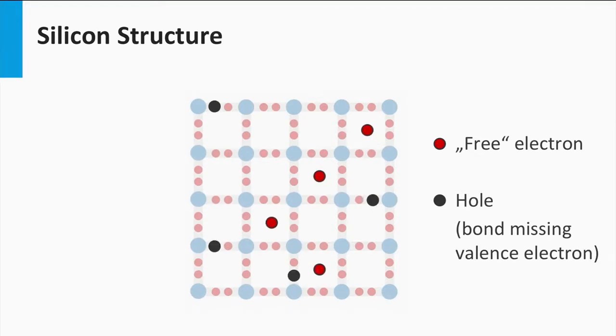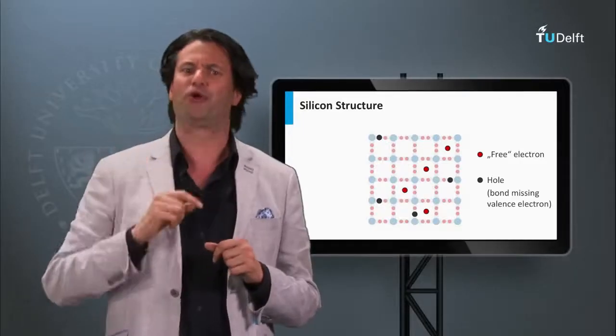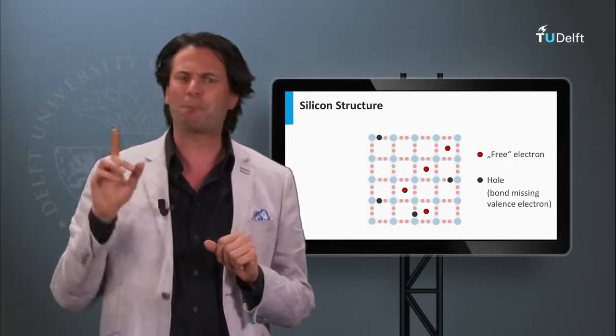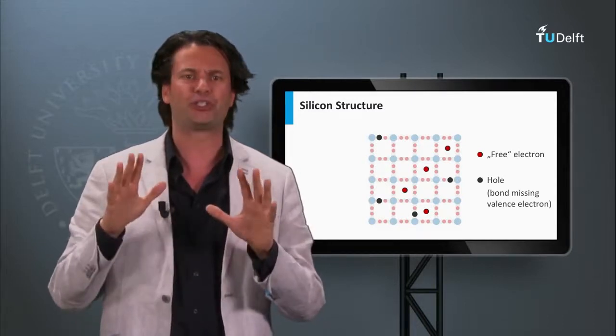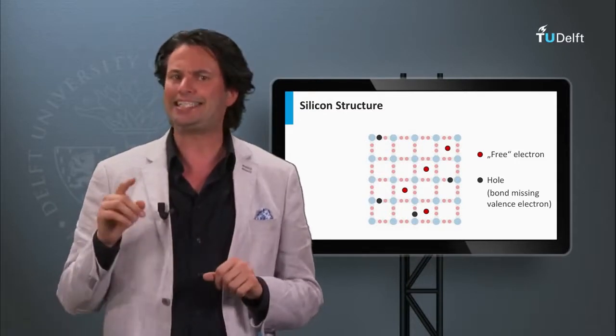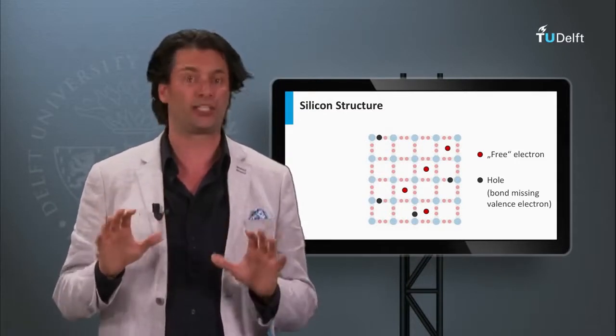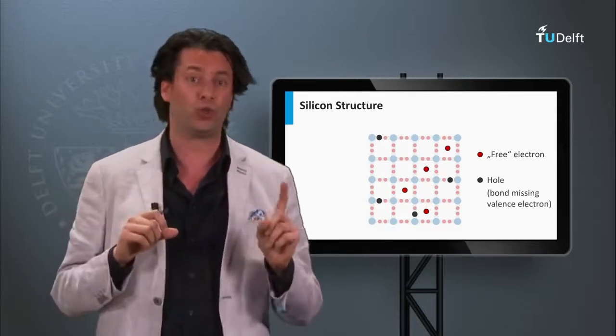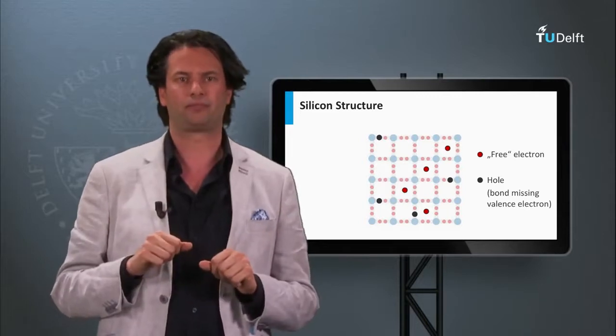So far, we have discussed that we can manipulate the density of the free charge carriers using temperature. The higher the temperature, the more free electrons and free holes can be excited. Another approach to increase the density of the charge carriers is using doping. Up to now, we have considered pure semiconductor materials without any impurities. These semiconductor materials are called intrinsic. It means that the density of the mobile electrons and holes are the same in the material.